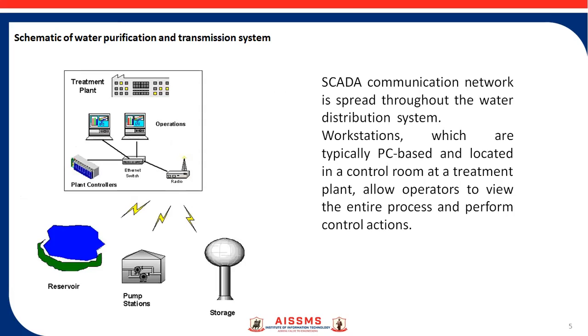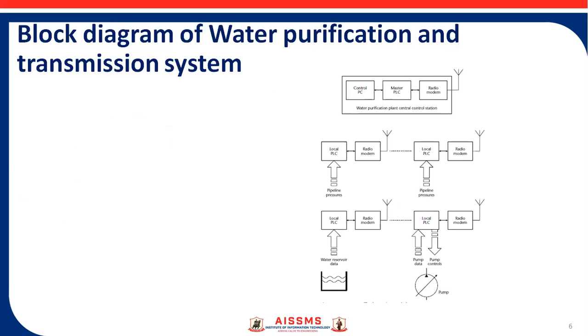SCADA communication network is spread throughout the water distribution system. Workstations, which are typically PC-based and located in a control room at a treatment plant, allow operators to view the entire process and perform control actions. This figure shows block diagram of water purification and transmission system.